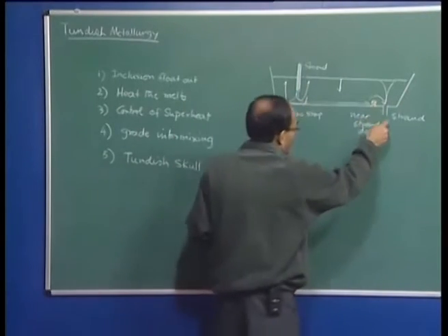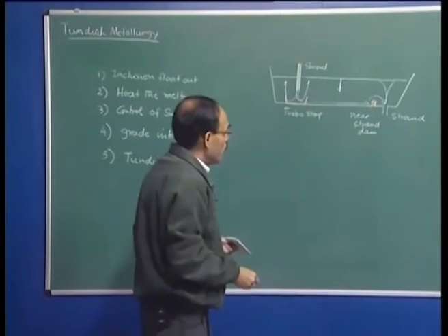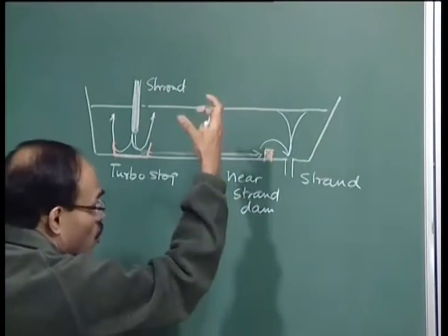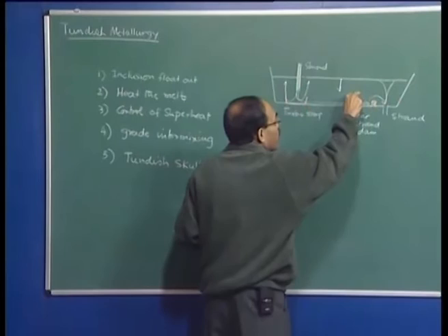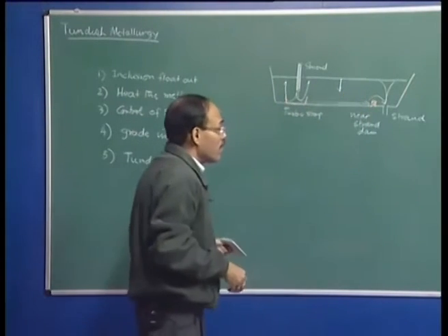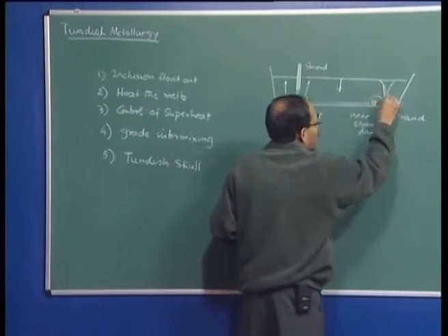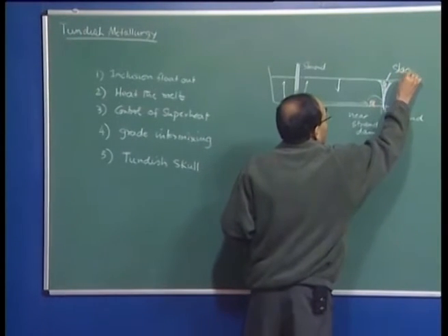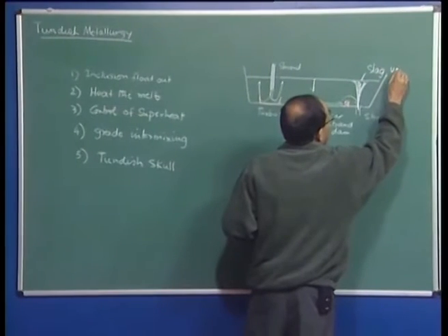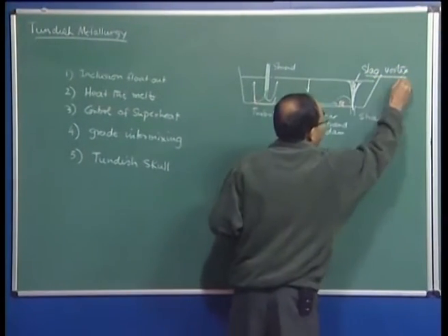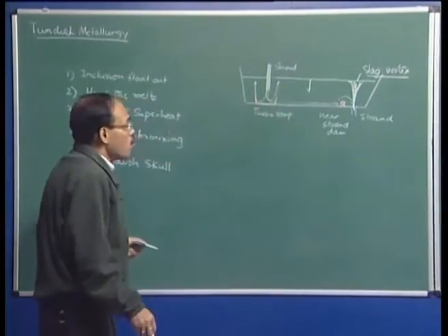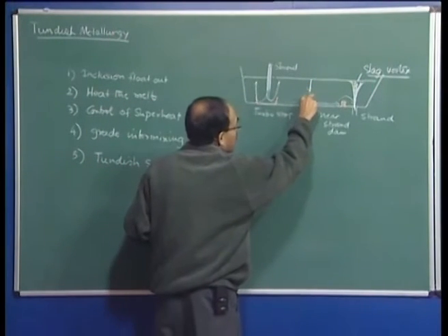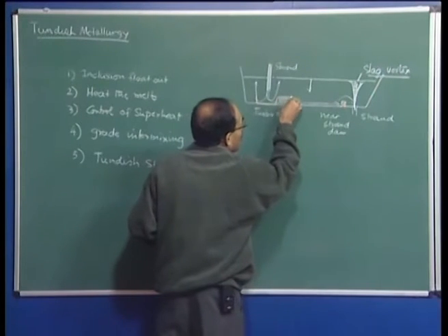This is a characteristic of draining vessels, also in ladles and tundish. Through the strand or through the well in the ladle, we have vortex formation or slag entrainment when the level of the metal falls to a threshold level. And if this slag gets into the mold, then we have a lot of problems, in terms of breakouts in the mold and so on.